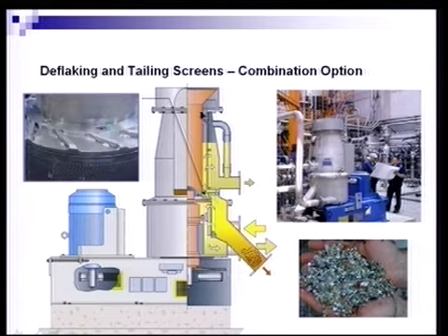The balance of the material then progresses up the rotor and is delivered out the chute, which then ends up looking like this debris here, which is essentially a fiber-free mass of nothing but plastics, rejects, styrofoam, rubber, that sort of thing that ends up in almost every recycled fiber papermaking plant. So this is a good combination screen that allows us to do 2 or 3 functions in one unit and still economize in terms of floor space, capital cost, and operating cost.